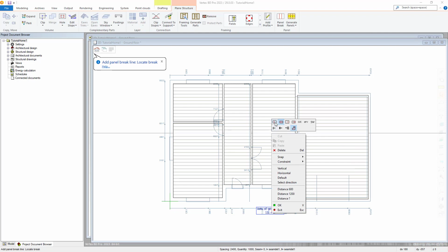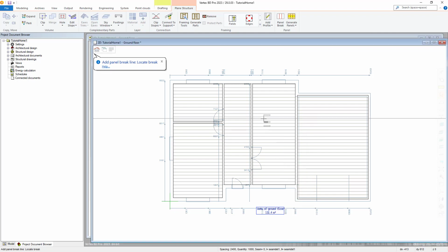Panel breaks added in this way divide the area into fields, into which you can also add panel breaks. Select an add-in method from the contextual toolbar. These options cover adding in by whole area, whilst this covers adding into fields. Here you define seam width and detail between the panels. Now click a location for the panel break, or a point from which the division is started. Once you've added all the breaks you require, confirm or quit out of the command in your preferred way.